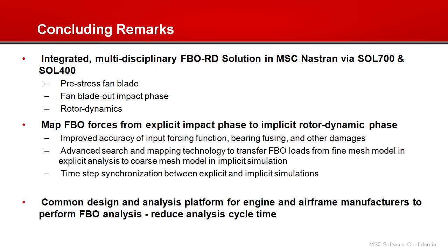For example, the implicit code assumes that the rotor is axisymmetric, but it becomes totally non-axisymmetric as soon as the fan blades get released. On the other hand, the explicit solvers have very small time steps, and it is really impractical to run the entire event for many seconds, especially with a few million element model. That's why we came up with this methodology to address what customers need and streamline the engine certification.